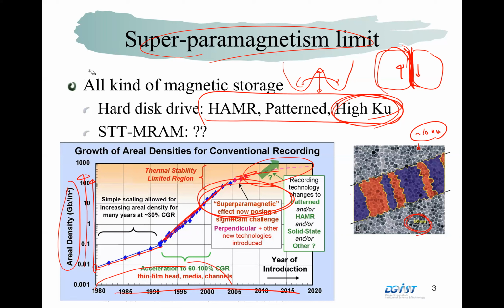So actually, there have been many tries to overcome this kind of problem. You know, nowadays the charging time is getting faster and faster, but it requires higher voltage, right? Higher voltage means the required energy barrier is high, but by applying the higher voltage they overcome such problems. But that means the battery is getting unstable, or the lifetime of the battery is getting worse. That kind of trade-off is really difficult to overcome by engineering because it's a physical limit.